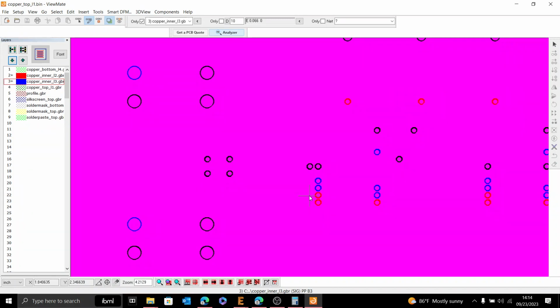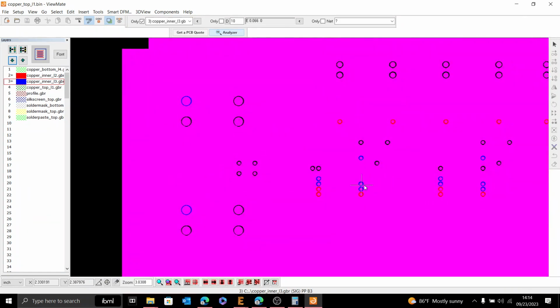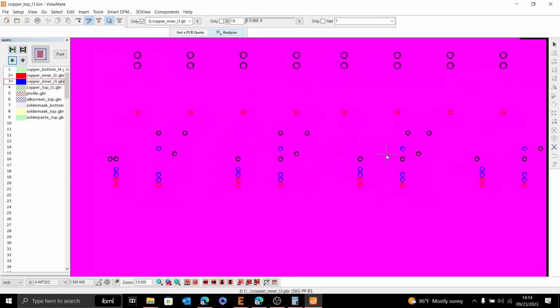We're not really sure how it happened. Maybe a weird net routing issue on OrCAD or something. I probably messed something up. But yes, the solution to fix that was to take the board, go to a drill press, and drill out the via. After we did that, it worked beautifully. So I don't know why that happened, but that's another thing you might want to check out. Just make sure your vias are routed to the right place. So you can turn them on and they'll mix the colors nice and pretty for you, and you can just give it a spot check.